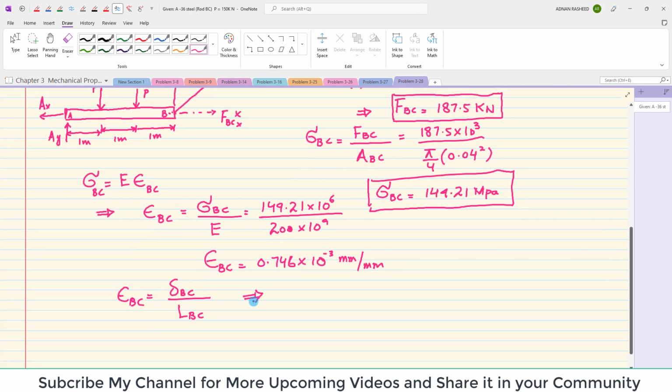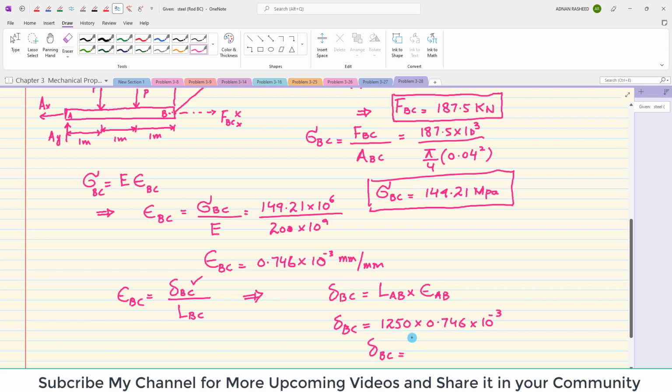We are interested in finding the change in length of BC. So change in length of BC is equal to length of BC into strain BC. Length of BC we have calculated, that was 1250 millimeter, and strain is 0.746 into 10 raised to power minus 3. So we will get change in length of BC equal to 0.933 millimeter. So this is the answer of our first part.